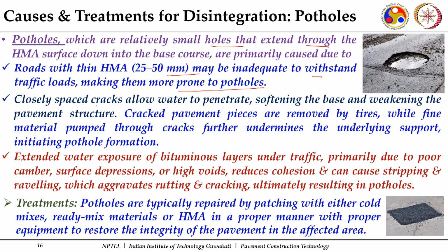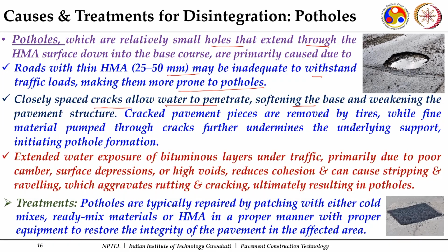When the thicknesses are less, crack formation may be there, and as we have seen, fatigue cracking, longitudinal cracking and transverse cracking are there. When these cracks are formed, water enters into them, softens the base and weakens the pavement structure. Then more stresses get generated and it will further break down.